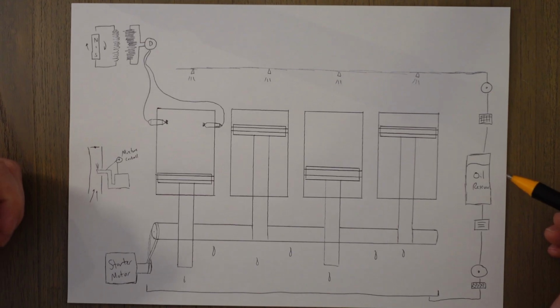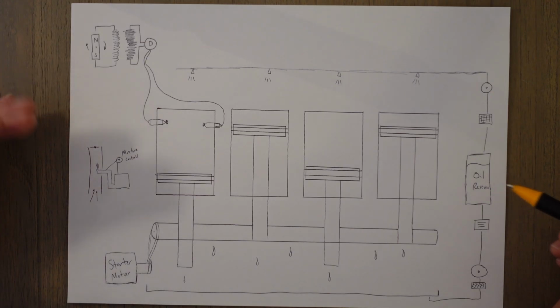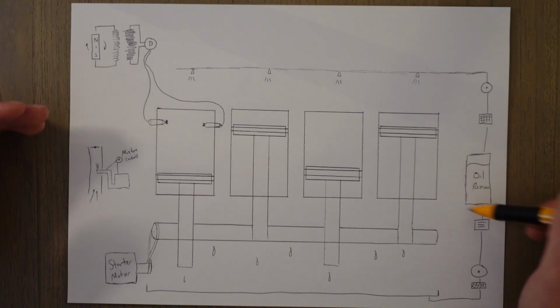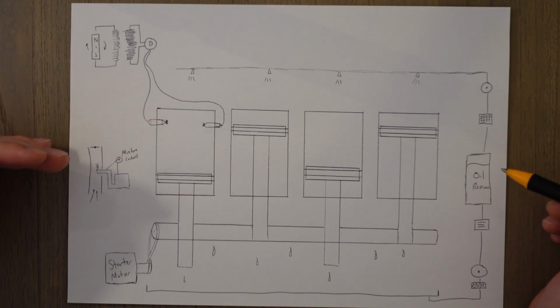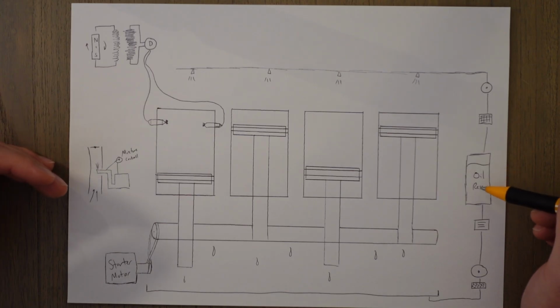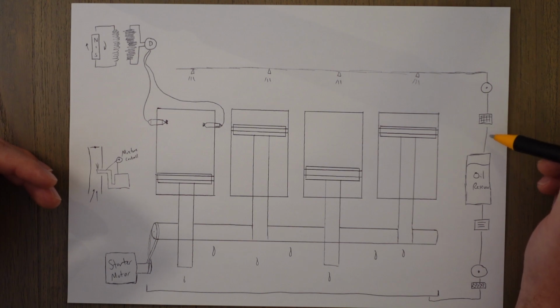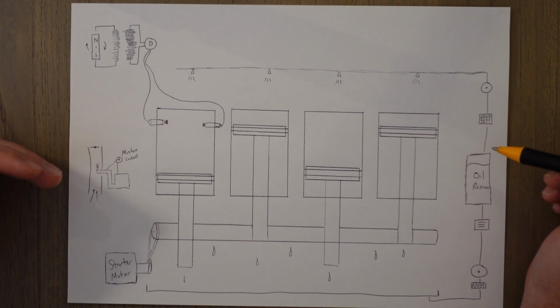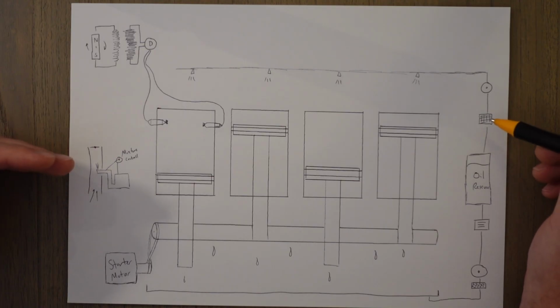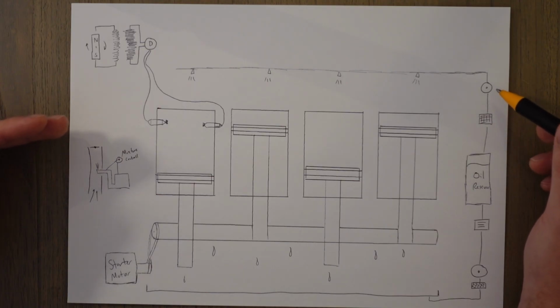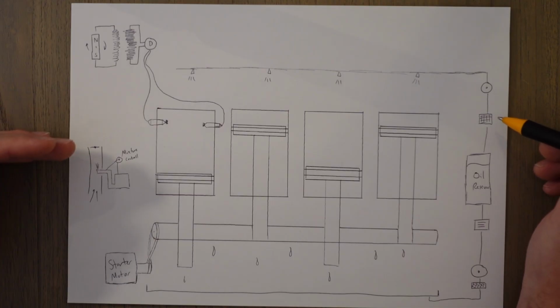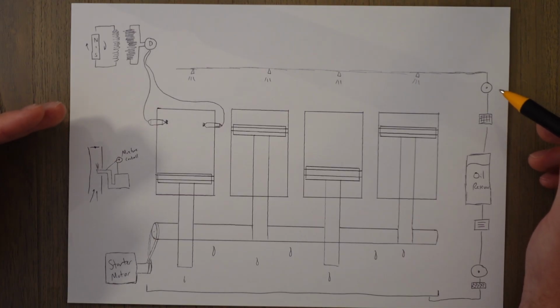We've got oil systems. Oil systems can be either dry sump or wet sump. This is an example of a dry sump. We've got an oil reservoir that contains the correct viscosity oil that we need for flying. It is sucked up via an engine-driven pump. Before that, it passes through a filter. Filters are good because they get rid of any contaminants in the oil, and those contaminants might damage the pump. It's much cheaper and easier to replace a filter than it is to replace a pump.